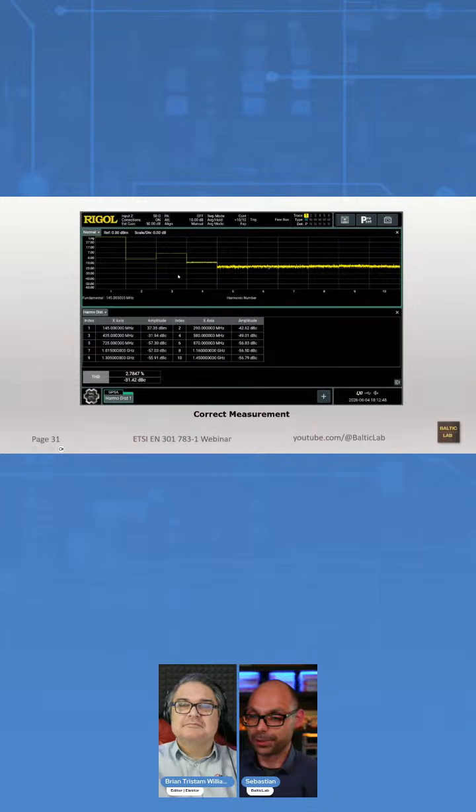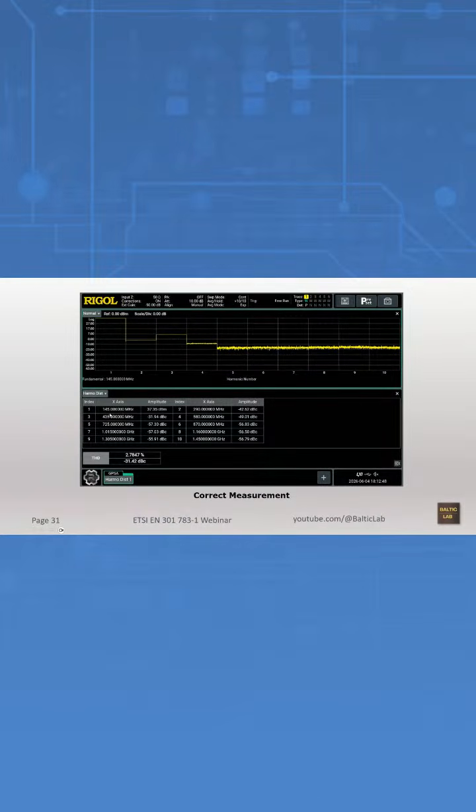Here is the measurement, by the way, with the harmonics function of the Rigel RSA 6085. So what you see down here is the frequency, the harmonic number, and then the amplitude for the fundamental absolute in dBm, and then the rest is in dBc. And this thing fails horribly, by the way, like the third harmonic. Wasn't there one that was worse? No, it was a different radio. Minus 70 dBc is kind of our target, and we're far away from that.